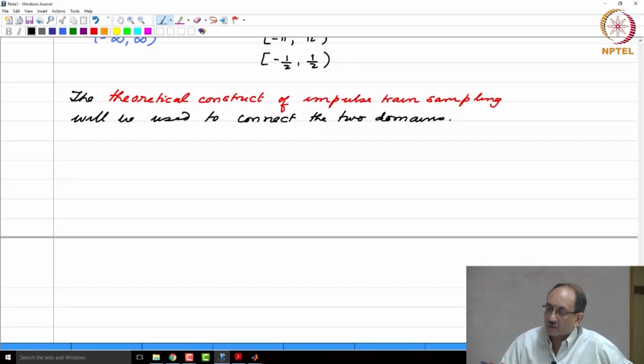And in this context it is good to remind ourselves that the higher the sampling frequency needed, the more expensive the circuitry becomes, because if the signal has a very large bandwidth, if you want to satisfy the sampling theorem constraints, you have to sample it at an extremely high frequency. So, which means the hardware required will be more complex. The other thing is, if you have very high frequency, it also means that the signal will vary more rapidly, right. That is what it means when you have very high frequency content in the signal.